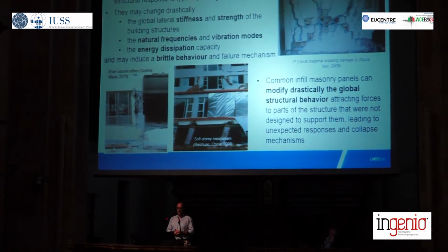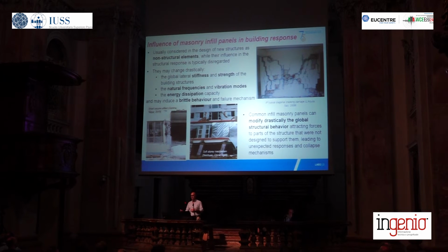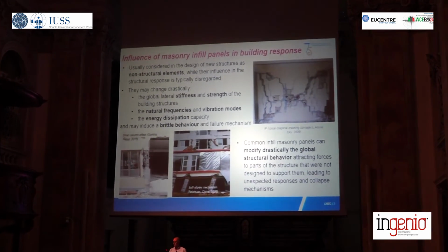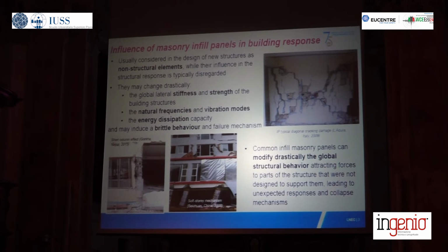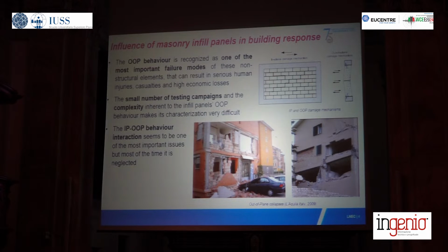So we all know about the influence of masonry infill panels on the building response, be it by changing the strength, the stiffness, or the failure mechanism that we get. So we may get short column effects, soft story mechanisms which we were not expecting. We have in-plane damage in the infills, but we can also have significant out-of-plane damage, which can cause fatalities, as we have seen in recent earthquakes.